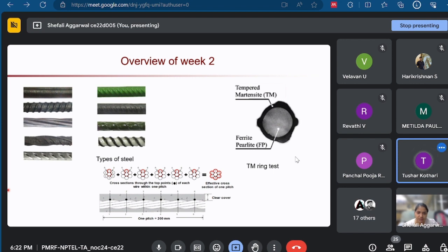See, even if you increase the thickness of the epoxy coated rebar, you can improve the bending quality. But in our Indian scenario, we can't ensure proper transportation of these kinds of rebars. These epoxy coated rebars have many defects. It's not just about the bending. When we are transporting it, there are chances that scratches will form, and because of those scratches, this coating will be disturbed, right?